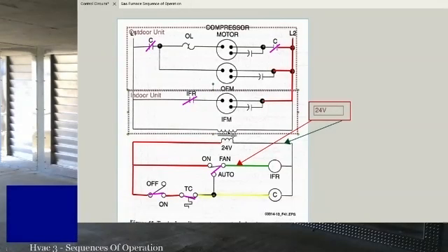With residential, it's the opposite. If I got 24 volts and everything is working just at the outdoor unit, but something's wrong in the indoor unit, I generally already know I have power and everything at the indoor unit because that transformer is working. So it must be the relay, fan motor, capacitor, or a low voltage problem with getting power to G, which is going to power my indoor fan relay.